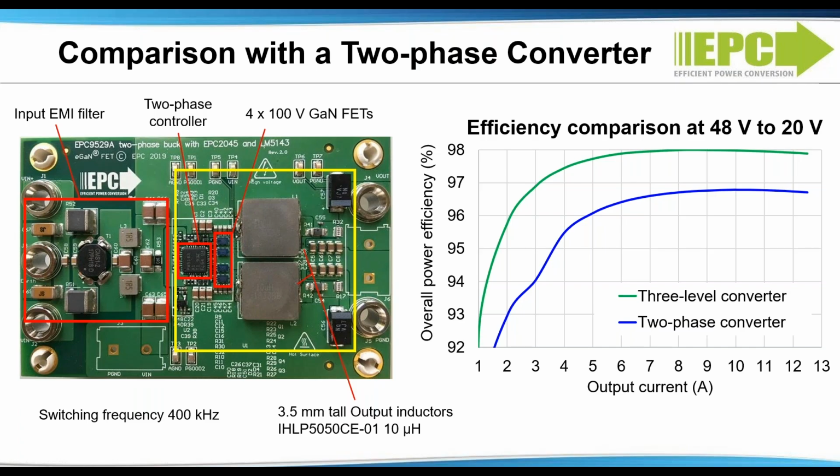And in both of those extreme cases, the efficiencies of those converters is 90+%. So you can really get a lot out of FETs. I think Steve Sandler, for those of you who know him, was trying to see how fast he could actually measure, and I think he measured 140 picosecond switching on our eGaN FETs. So that's pretty fast. You can go pretty high in frequency.